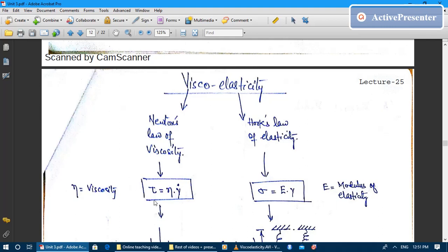So the viscous behavior of polymer is contributed by the intermolecular secondary attraction or interaction among the chains, and these interactions may be deformed when the polymer is loaded. Hydrogen bond may break, dipole attraction may break, van der Waals forces may also be overcome. So intermolecular attraction can be overcome during the loading of the polymer. Okay, and when the chains pass over each other at the new location, new secondary bonds can be formed.